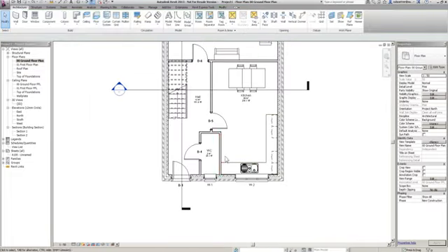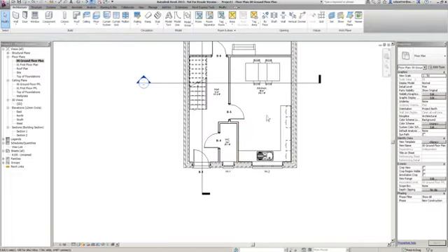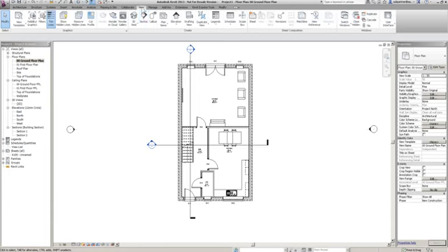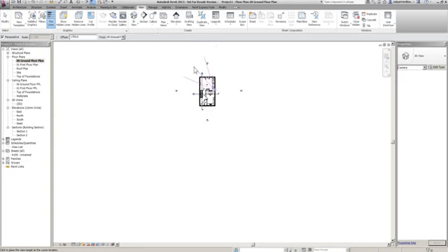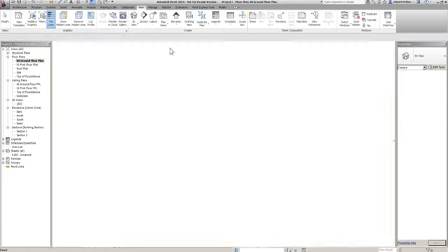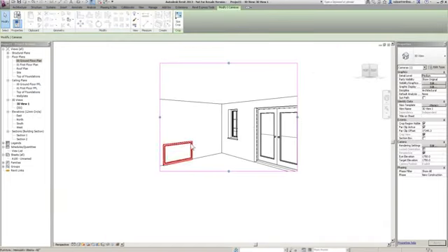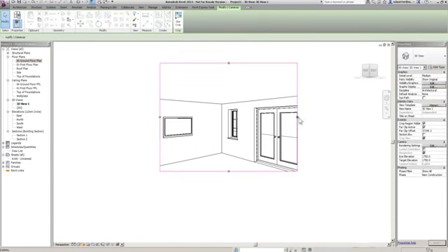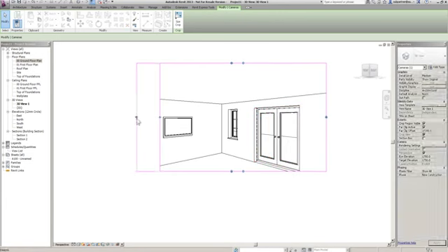Okay, now what I'm going to do now is place in here some cameras, because we haven't seen the cameras yet. So I'm going to go to either my quick access toolbar just here, or under your view tab just here, throw a camera in. I'm going to throw a camera in looking outside my building. Always take the focal point beyond the building. There we go. Schoolboy error again. Okay, it's on the floor. That's no good. Okay, let's place it up just there. Fantastic. Once the camera's in, let's just drag this. Don't drag it too much because it will obscure it if you're not careful.